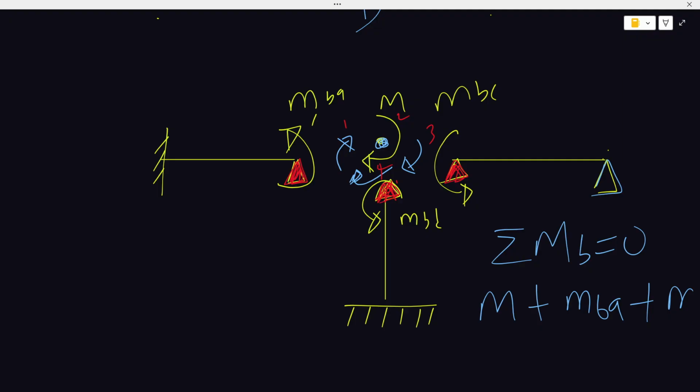This is a hinge. So these red shaded parts are hinges. So if this hinge and this moment here represent my applied moment, it means that MBA is my applied moment, and it will be equal to 4EI theta over L, because it is the same thing as saying that B is my near end now and A is my far end.